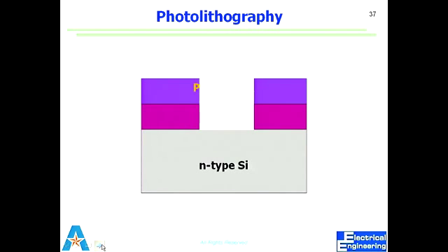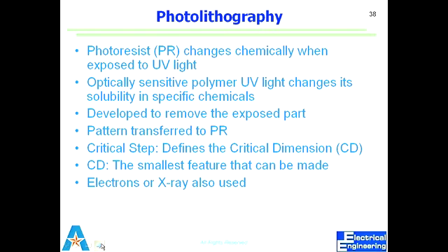When I'm saying hard, photoresist is just a polymer. If you put a scratch on it, even if you touch it with your finger, you'll see it's going to have grooves from your finger. Anyway, so this is what we do. Then we remove our resist, and now we have our pattern transferred. So this was, I'm just showing you. The actual thing will be a two-dimensional surface with all the openings for sources and drains and whatever. So essentially, this is what we do. So PR changes chemically. It's time. Question.